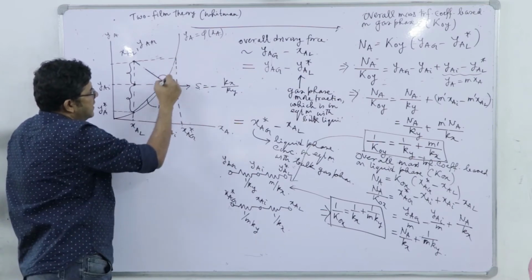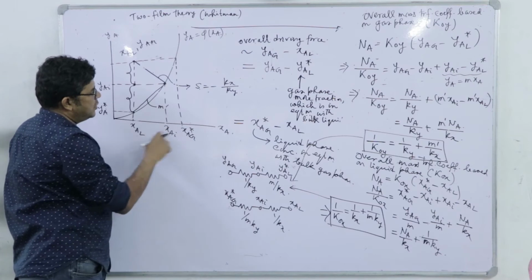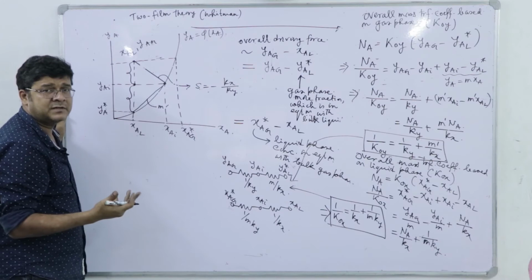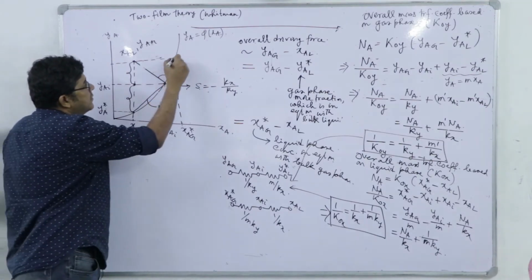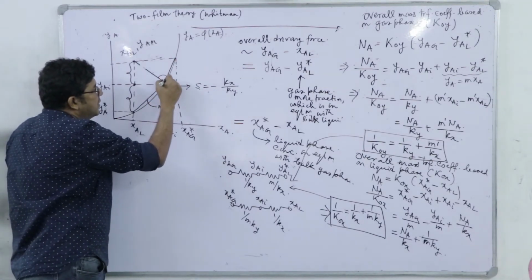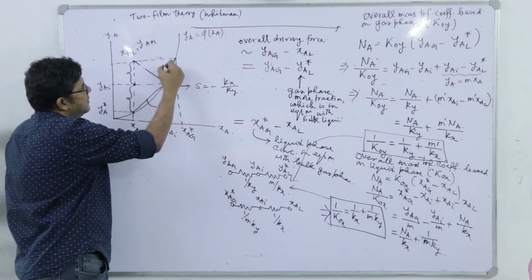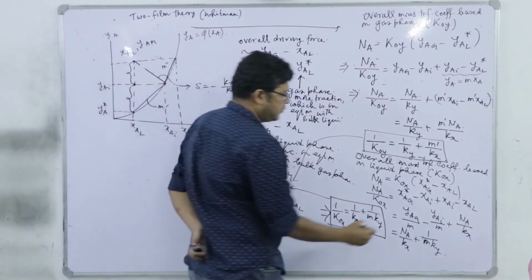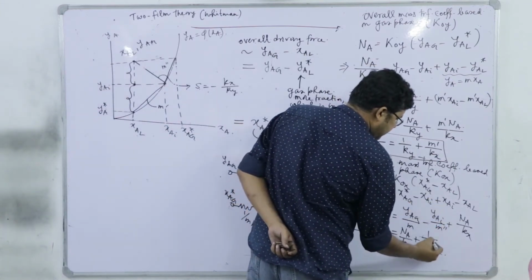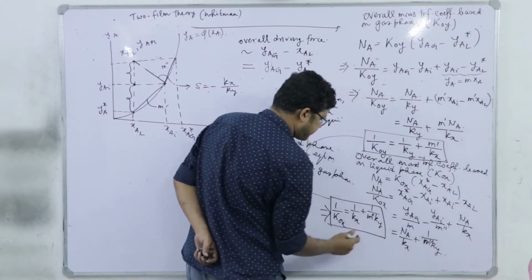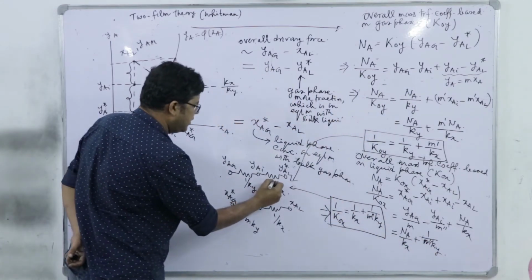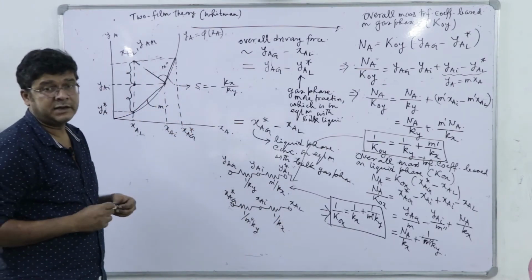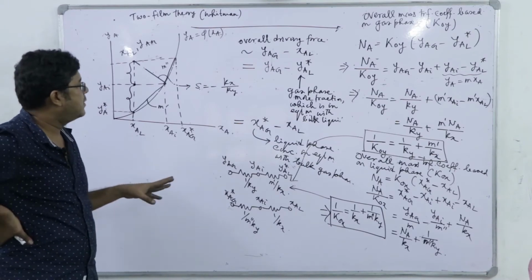We are looking for this segment of this equilibrium relation to transform this gas phase driving force in terms of liquid phase composition. So, respective linearization will yield slope m double prime. So, here we should use this m double prime truly, and we will get this sort of relation. So, this is m prime and this is m double prime in case of nonlinear equilibrium curve, right.